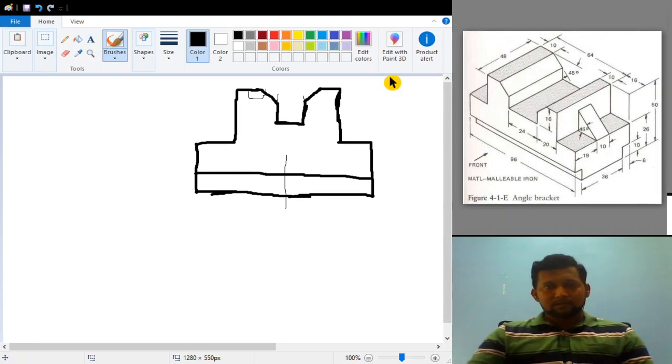Also, one more thing that I have missed here: in the front view you will be able to see this right angle triangle also. So from a distance of 25, this particular point is this particular point. Why? Because this particular point merges with this entire distance. Because in the front view this entire distance becomes 0.